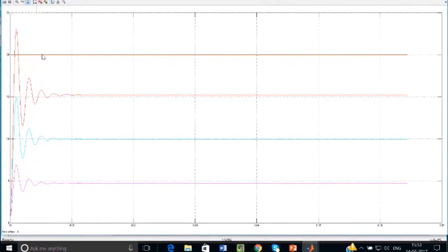I think it is a little visible. So this is the 20 volts input we gave, and according to that, 0.5 gives 10 volts, 0.75 gives around 15 volts, and 5 volts when it is 0.25. Okay, so it is not perfectly matching.